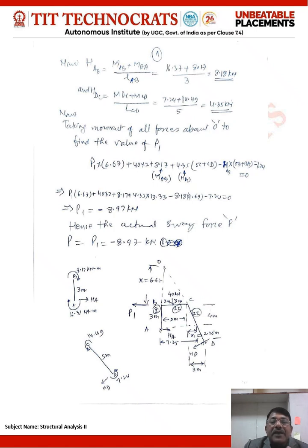forces as indicated here as per the figure. You can notice I have drawn everything very clear here. This is the figure pertaining to the computation of the horizontal reaction at D, or reaction along HD. This is the figure by which you have computed the horizontal reaction at A. Notice that the moment at A is clockwise in nature, moment at B is clockwise in nature. So therefore the direction of HA should be such that HA must make some anti-clockwise moment at B. Notice, place the direction correctly so that you don't make a mistake.